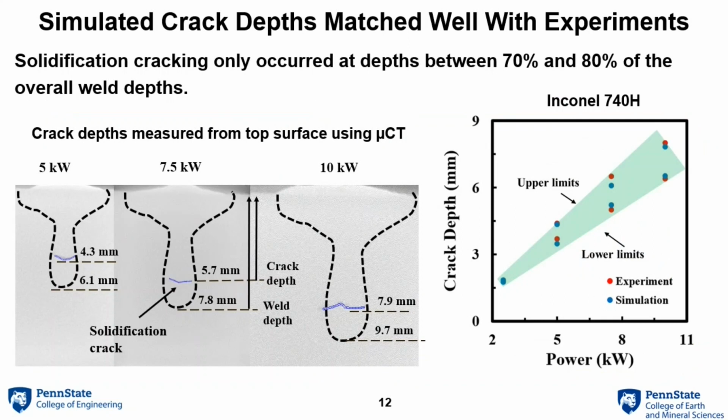We can then extend the calculation to some other welding conditions, basically different laser powers in this case. We can see from this plot that the simulated crack range matched pretty well with the experimentally determined crack range, which indicates that our model is able to capture the conditions driving the unique solidification cracking behaviors during high-power laser welding of nickel alloys.